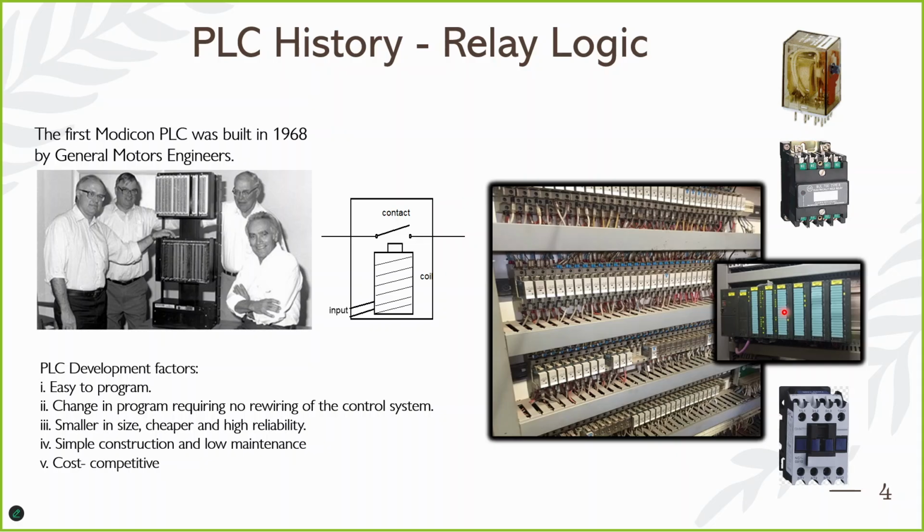Rather than having a full control panel like this as a spare, which is not possible, what people usually keep are spares of the relays themselves. And when there is a breakdown, in most cases you have to switch off the whole system so that you can replace each of the relays.